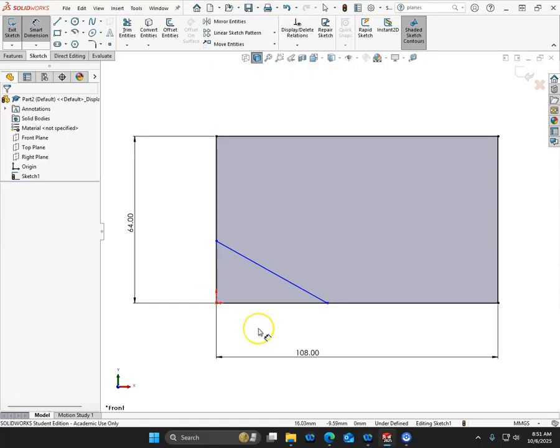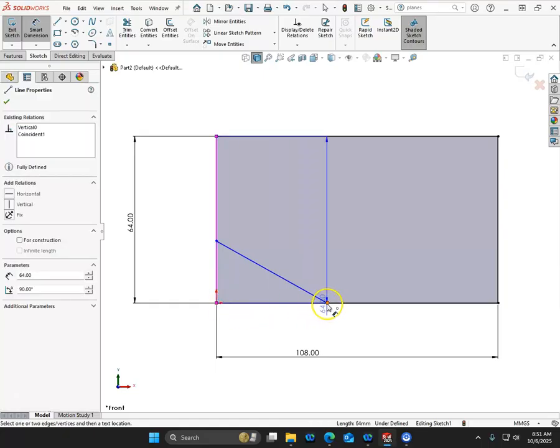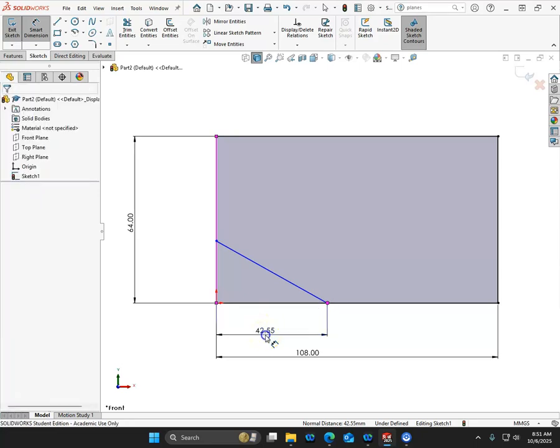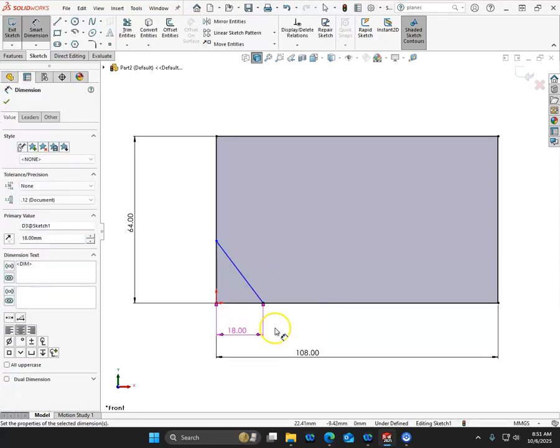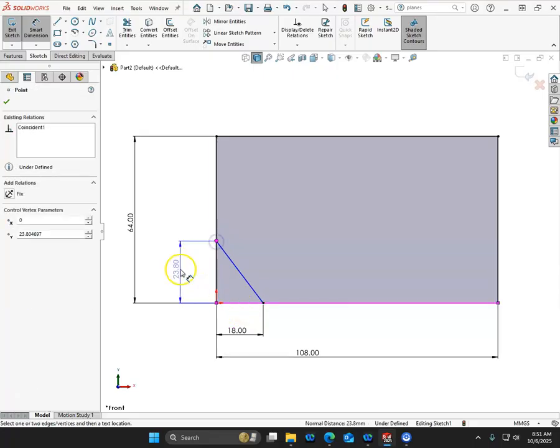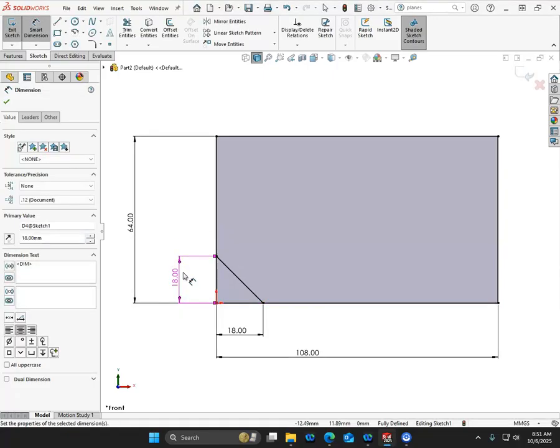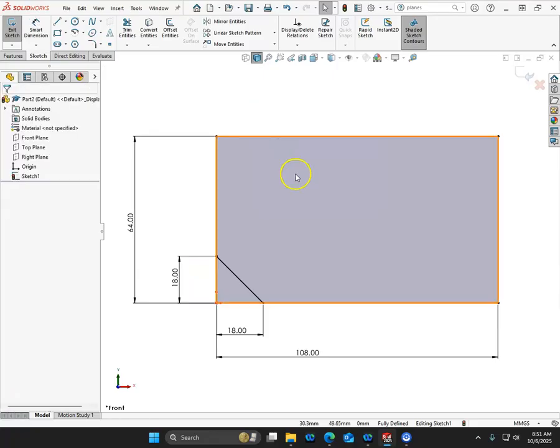So putting the dimensions on. If I go from point to point, that should still be okay for the vertical and the horizontal. When you pick an edge or a line, then it is going to build that geometry, and typically that edge is going to be an easier selection than going to the point. So I'm still going to recommend object and that you build your geometry. So right click, get back into the select to kind of decide what I want to do next.